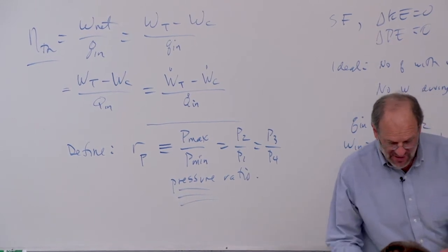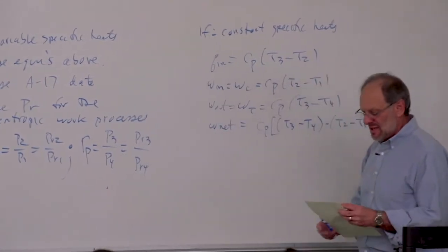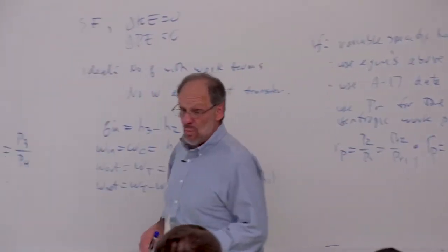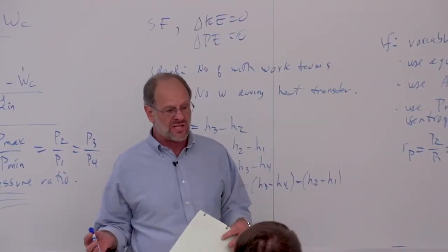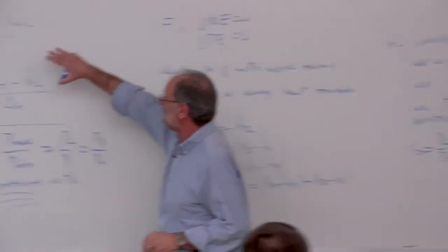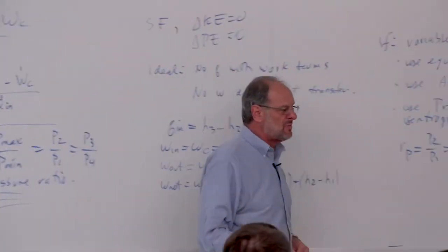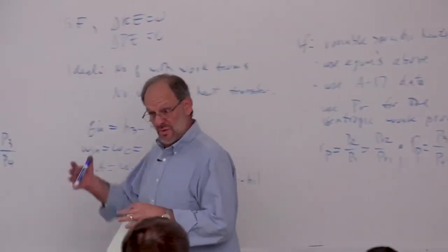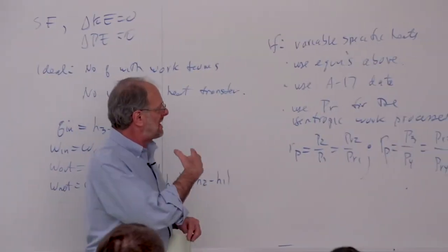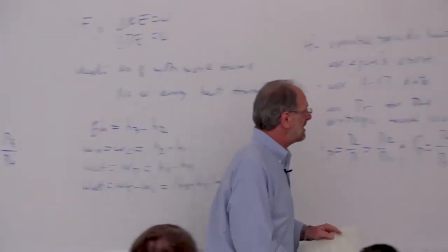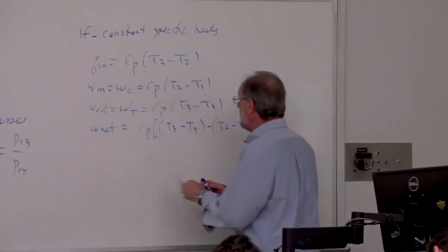And then something that should also be noted is that we can modify these equations a little bit in order to find a simpler version of our equation for the thermodynamic efficiency. We did something similar when we looked at both the Otto and the diesel cycles, right? We had an efficiency equation that was in terms of work and heat transfer, but through manipulation, we were able to adjust that equation so that it was only in terms of a volume ratio term. That's what we did for the reciprocating engines. Now we're going to do it, and hopefully we'll get an equation that's only and entirely in terms of just the pressure ratio. So let me just go through that very briefly.